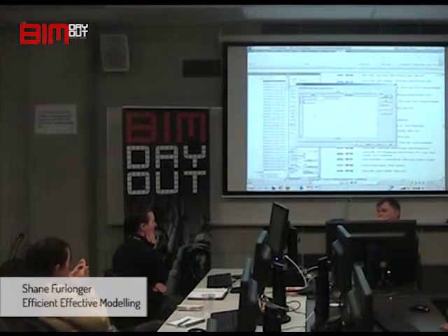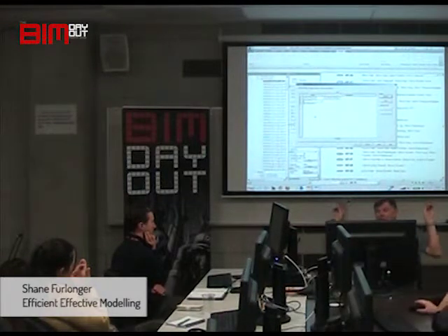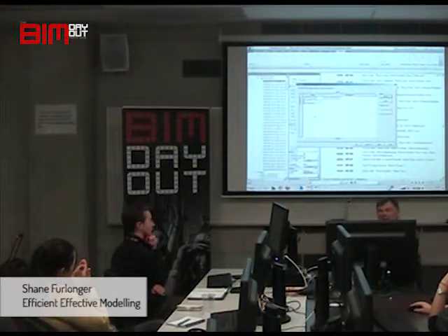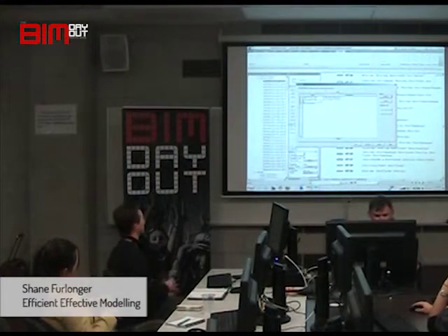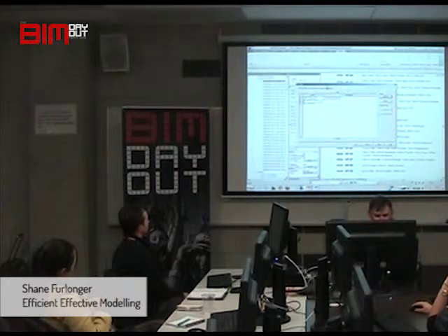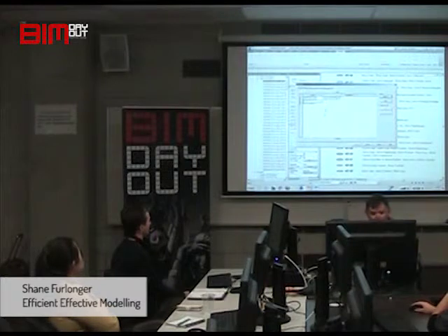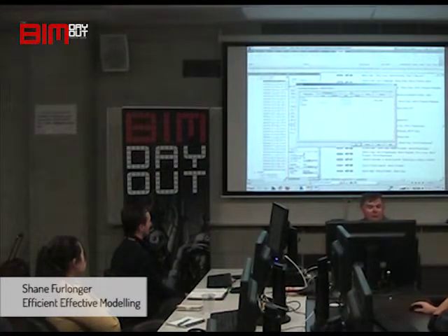So the best way to explain it, like doing the extensions, what the building was would go into phase 1, or existing, and then what you put on new, you would put in new construction. And that way you can show, so in your graphic overrides, it's just going to take a second because I just changed that name there. And it's going through and changing everything in the entire project. I shouldn't have done that. Okay.